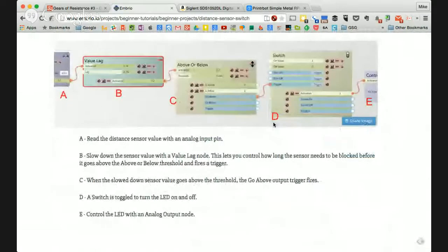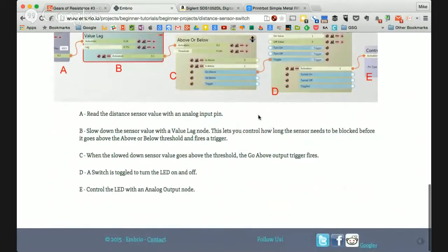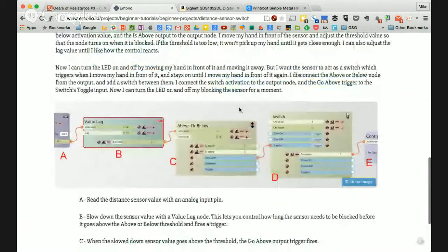Here we go. So as you're hooking up some sort of distance sensor, in this case an infrared sensor, you can get real-time readings into the code. Say you do a voltage divider circuit, right? If I put the variable resistor connected to the VCC versus connected to ground, I get a different behavior when I tap in and do the reading on my voltage divider circuit. Here you can see it in real time,